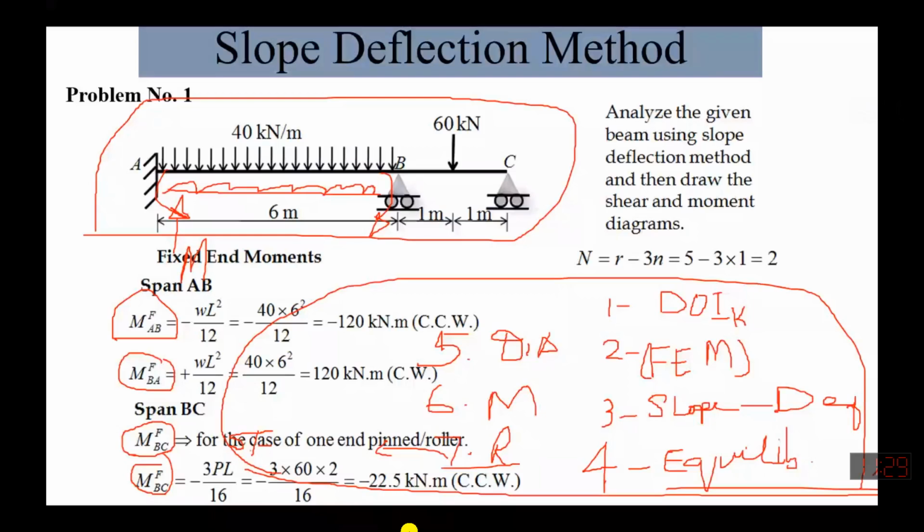So, talking about these steps to solve by the displacement method, in the displacement method we are applying the equilibrium condition, whereas in the force method, as we discussed a while ago, we apply compatibility first. In the force method we apply compatibility, and in the displacement method we apply equilibrium. Is it clear to you or not?